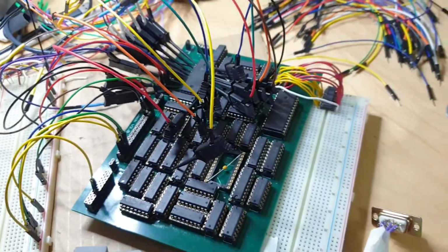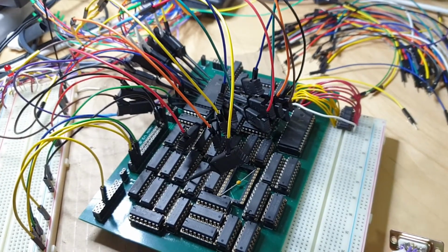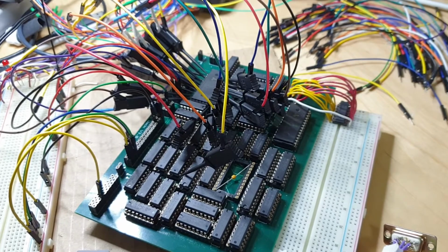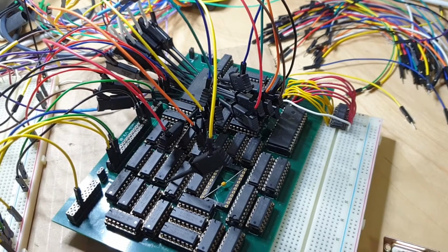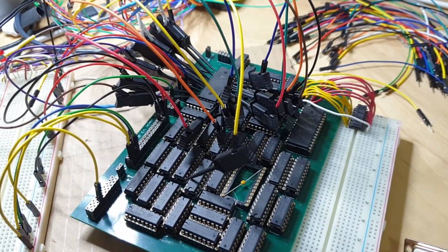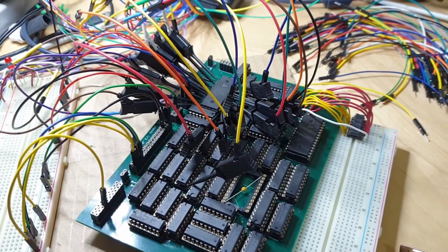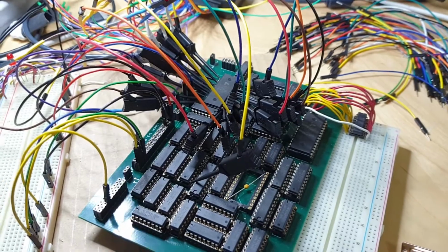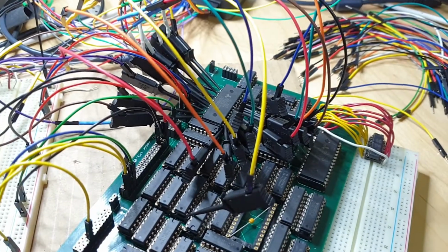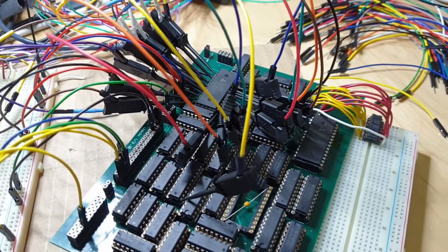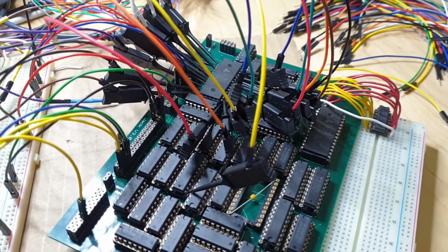Now this is the character generation board tested in isolation. It remains to be seen whether or not this all works when it's all plugged together. But so far, according to the logic analyzer, the memory write seems to happen as expected. And then when I don't set the extended memory bus address here, then of course the expected writes don't go through to the RAMs, and then the character generation board switches to read mode for these.